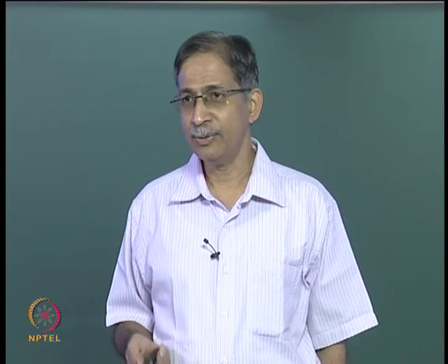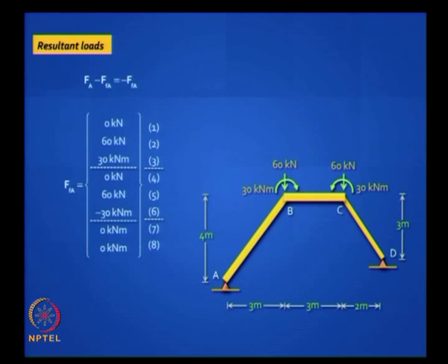Right, you can draw a sketch. Look at this. This is your resultant load vector. FA minus FFA. FA is a null vector because there are no nodal loads in this particular problem. You had only a UDL, and so FFA is given there. Put a negative sign to it and interpret those results. You will find that the original problem had a UDL.